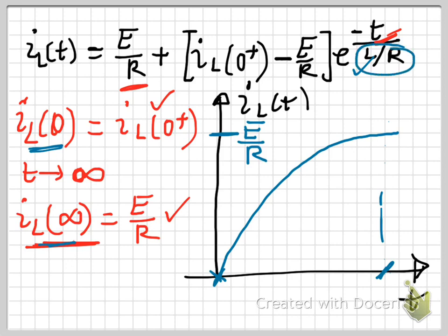It depends on the time constant, so L over R in this case is defined as the time constant, L over R is tau. In case of an RC circuit, it's R multiplied by C. So now it's L divided by R. Approximately at 5 times tau, we consider that whatever state the inductor reaches is fully charged or fully discharged. So 5 times tau is the time it takes.